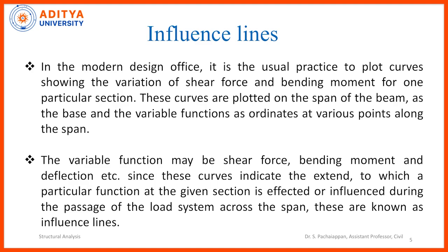In MATLAB programming or something similar, we give x as a variable: 1, 2, 3. So every meter or every 0.5 meters, we get all the responses. These curves are plotted with the span of the beam as the base and the variable function as the ordinate at various points along the span. The variable function may be, as I told you, the shear force, the bending moment, deflection, etc.